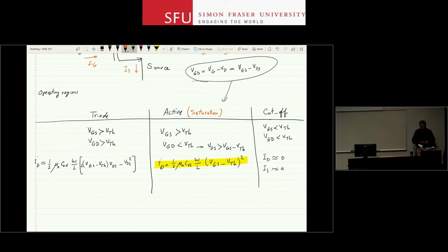Now, you may have a question here: we have this device that can actually be made smaller than a BJT. Nowadays it is cheaper to make than a BJT, and it can serve so many purposes. Why do I need a BJT? Why do we still keep those things around, if this MOSFET can do all those fantastic things and beyond? Well, the answer is that the MOSFET is a great device, but it falls short when compared to BJTs in terms of how efficient it is as a nonlinear device, especially in amplifier circuits and so on.